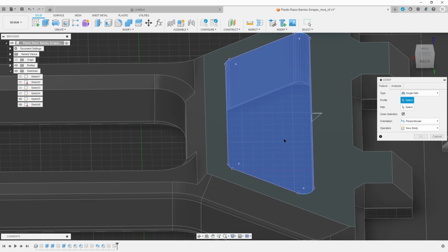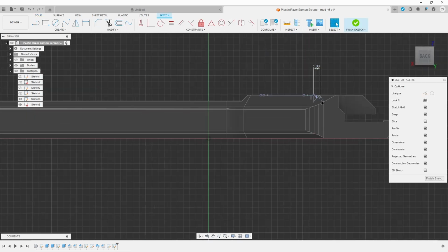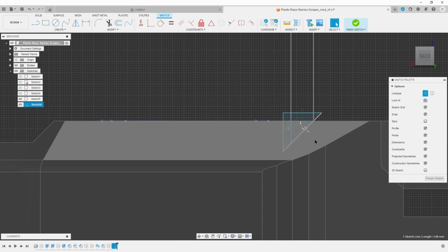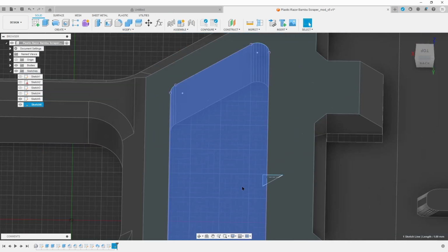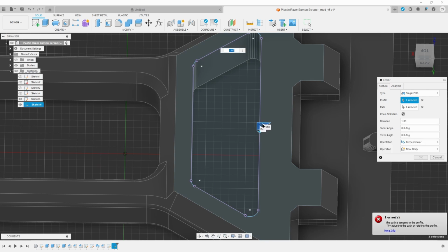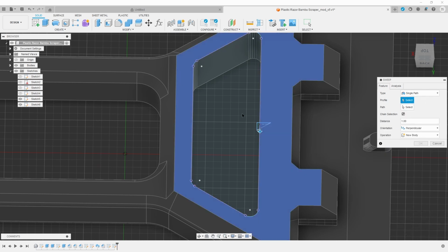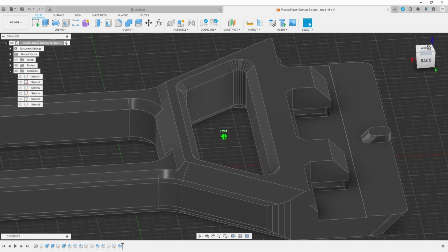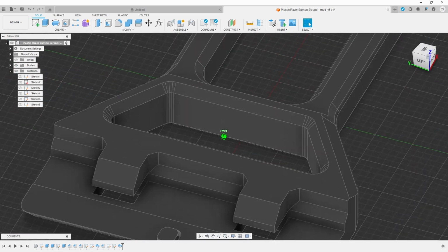You won't be able to select it here. You could use an inspect cutaway. But what I'm going to do, just to make it very simple to select, is add length to the feature and then turn that piece into construction geometry by clicking it and hitting X. Now when we go back into the sweep, it's selected things but it hasn't quite selected it correctly, so we want to hit the little X there and reselect our tool and then select our path, and there we have it. Quick chamfer even in tight radii where you can control it more.